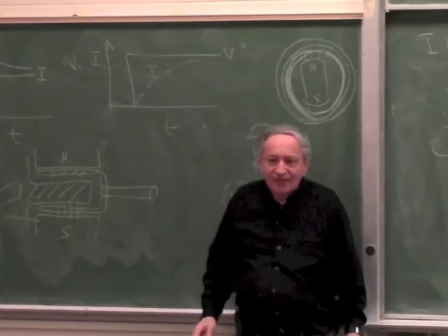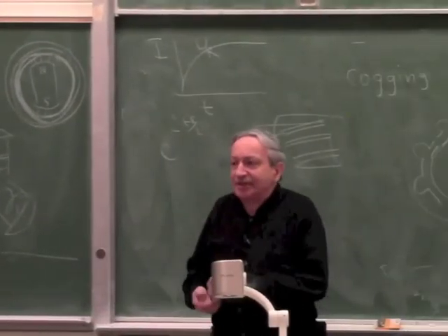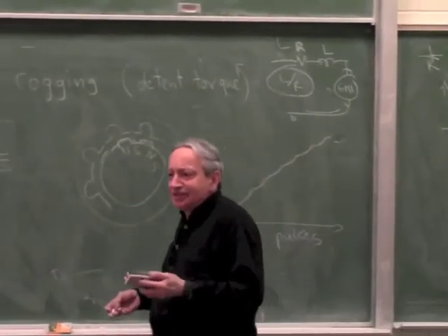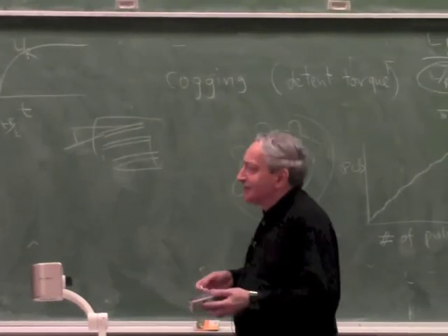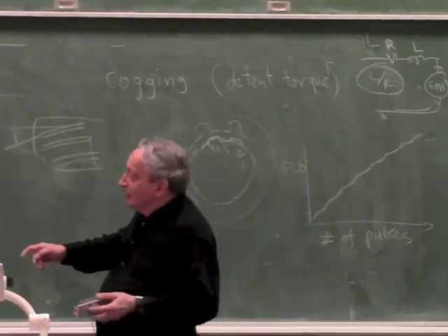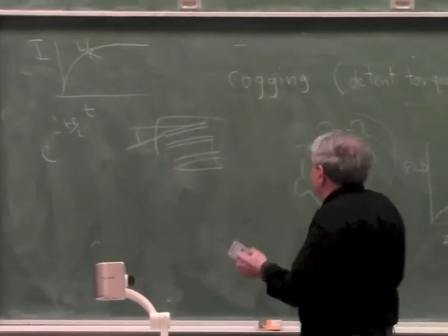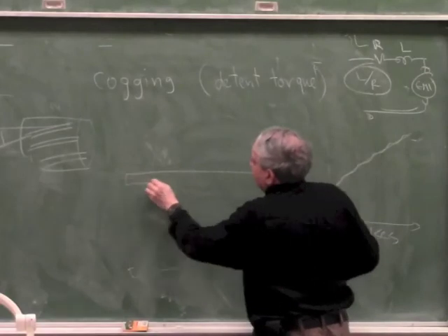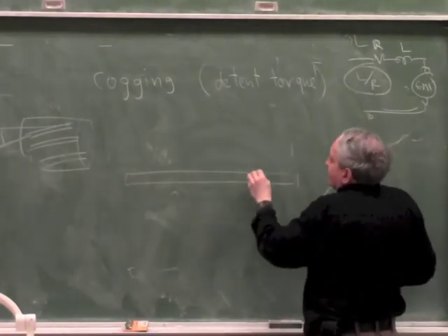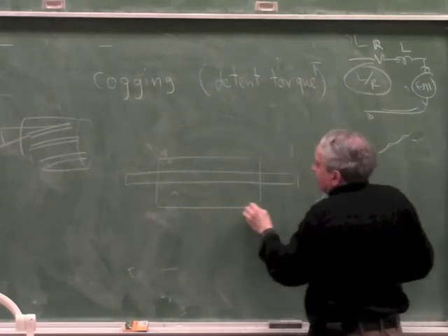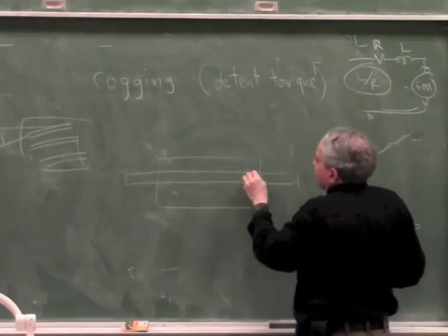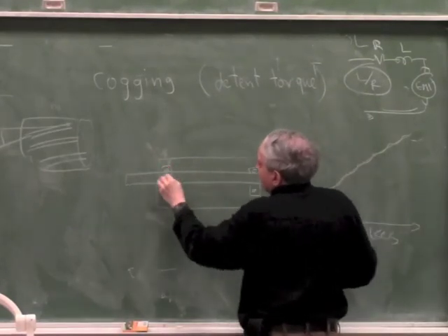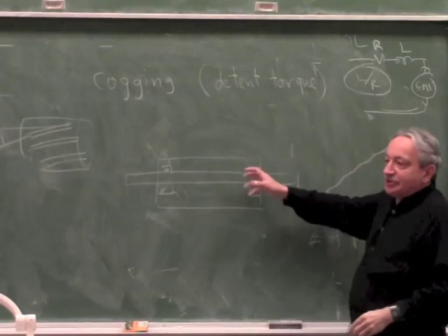Okay? There is actually a better way to build a DC servo motor, and to my surprise nobody does it. I mentioned in many other areas there is some obvious better solution which nobody does, like with the encoders. There is an obviously better solution to build a DC servo, but nobody does it, and I can't understand why. And this is to have a shaft, to have the magnet inside the shaft on bearings. So the magnet is sitting on ball bearings, either the magnet or a piece of steel, it doesn't matter. So the magnet can freely rotate on the shaft.